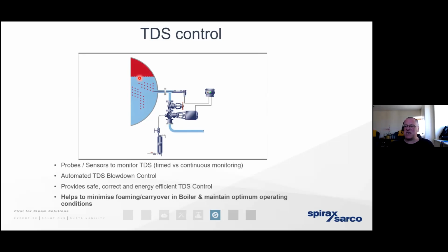It's going to be very sticky. So of course, we're going to get that erosion, corrosion, water hammer that we've spoken about. But that foam can also dry out and produce a very fine chalky scale. So that can contribute to erosion of sensitive areas. It can bind itself to heat transfer surface areas as well. But it can also be injected directly into a product or a process whenever we may be using steam for direct injection purposes. So it is a point of contamination there.